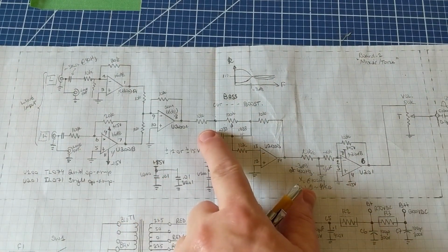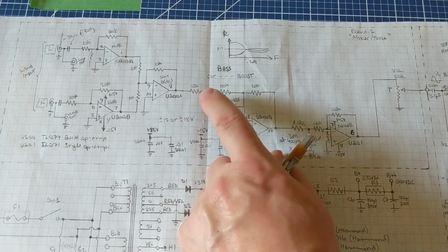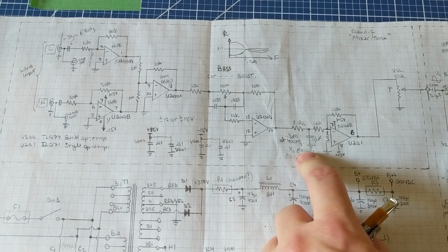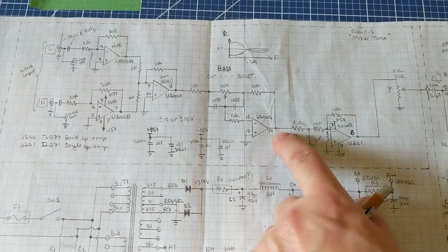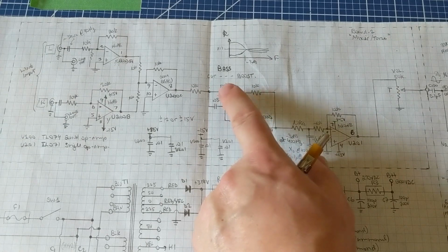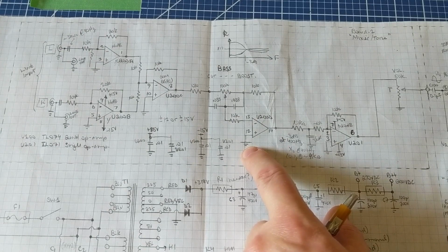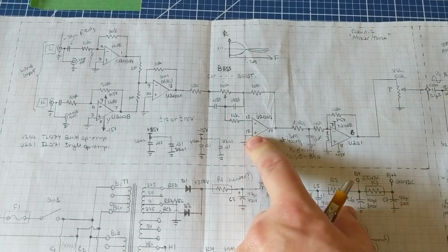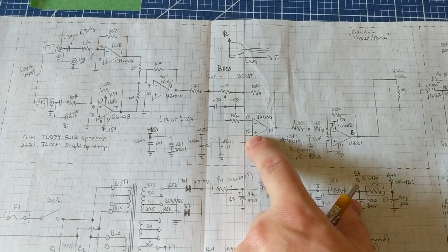This part of the circuit is a passive low pass filter. This is the active low pass filter, the bass boost cut. It uses the design from the application note I showed previously, and it uses an active feedback path to allow this thing to both have a gain as well as an attenuation. This design is actually kind of interesting, and it's fun to go through it and figure out how it works. I might do a separate video to talk about how that works.